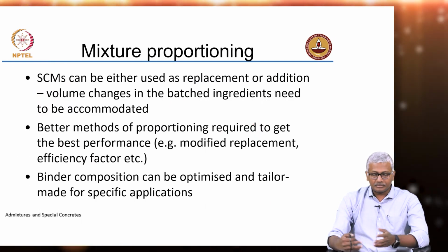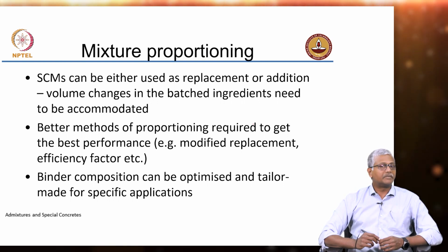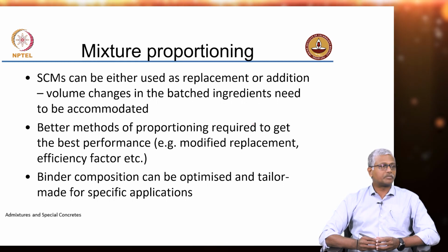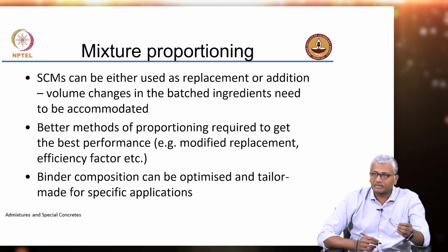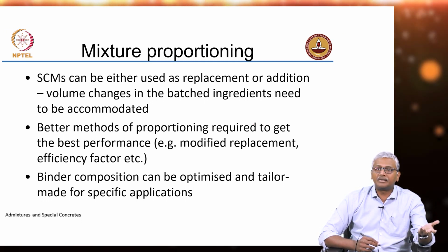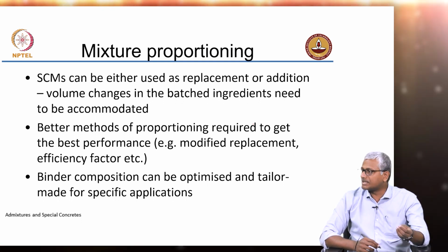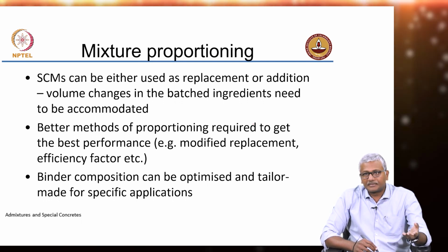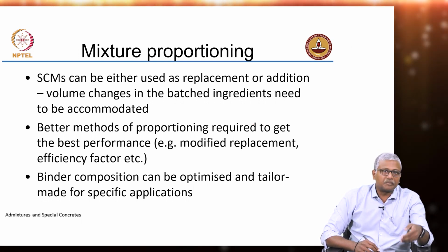So, in conclusion, with respect to the activity testing of materials, it is very important for us to adjudge the extent of reactivity shown by any mineral additive or supplementary material before we start using it in concrete. We can't really take a newly created material and start putting it as a replacement of cement in concrete without assessing what it can potentially do. Because if the material is inert, you are not going to be able to replace cement with that material.